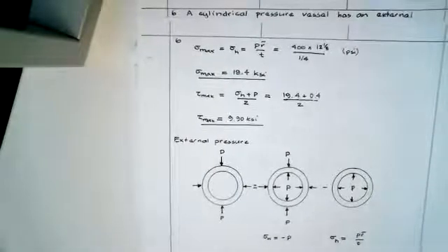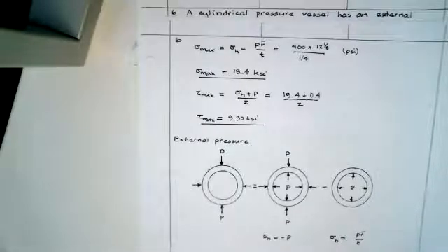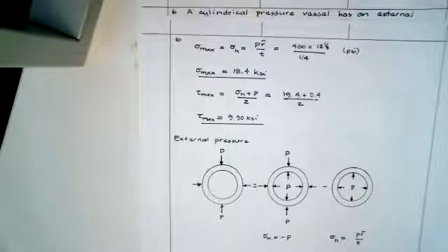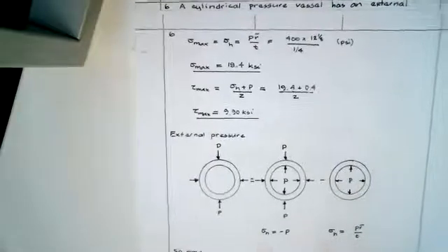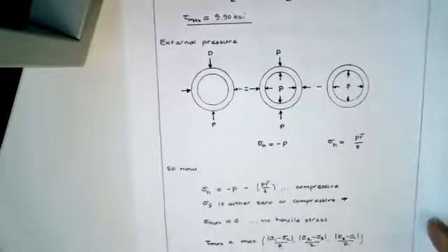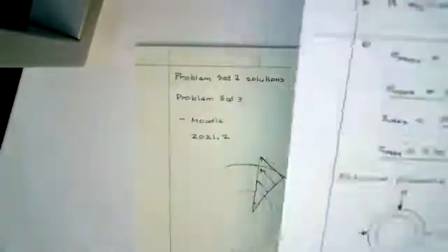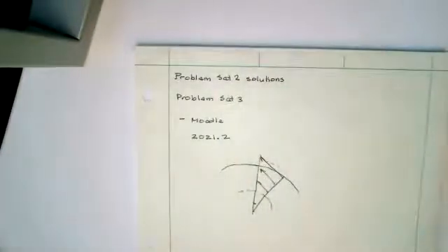Oh, and then the maximum shear, I'll let you think about this, but you don't want to take the minus P off because it'd be a negative compressive stress. Minus P would add a P, and that would make it smaller. You want to take sigma 3 with 0. Okay. And you get exactly the same. Okay. So here's the rule for external pressure.